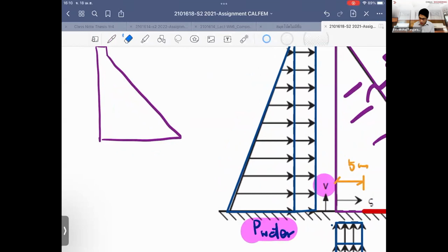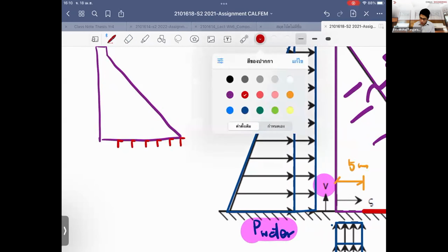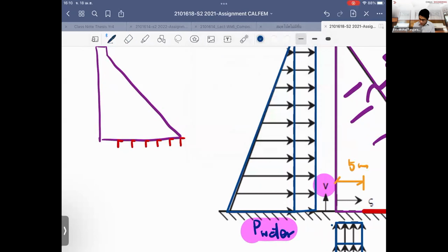I'm saying that, okay, I try to give the boundary conditions here. So this one, I fix them. Right. And I know there is a force. So I represent the uplift pressure with a single force, and I apply it to the centroid. And this, I say, is the uplift.